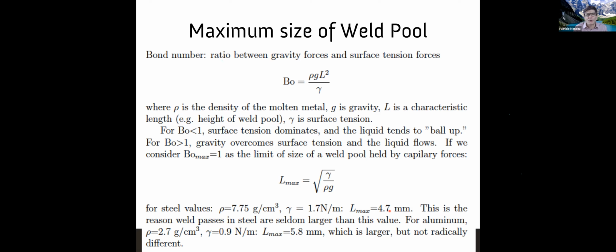So we already discussed this. Why would I use a flux core electrode if I'm using a gas anyway? Flux core electrodes give us a quality somewhat similar to MIG, but in addition, they give us a way of cupping the bead so it's not going to run crazy and we can make bigger beads. This is important, for example, in the case of vertical welding, out of position welding. Pretty cool.